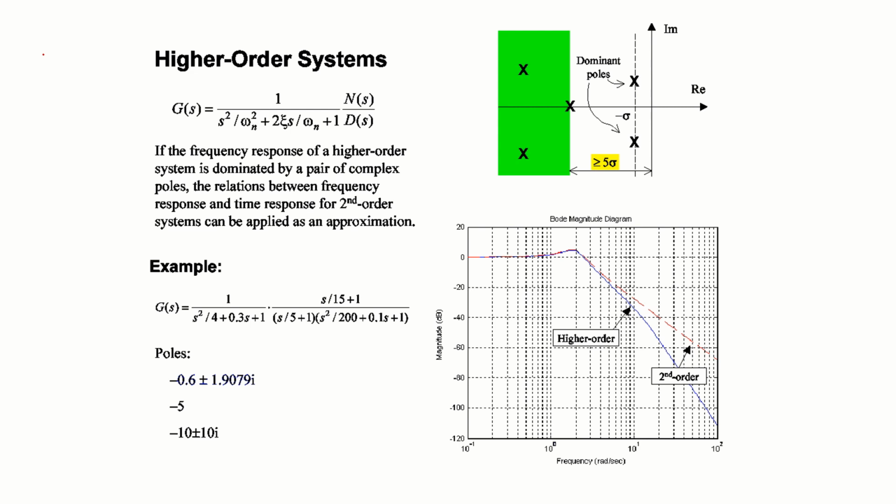What it means: suppose you want to understand the behavior of higher order systems. You see here in this system, suppose you have poles here and in this region. But these are the poles which control the system behavior. So this is what we call dominant poles. If the other roots are away, the response may decay faster, but these will not allow it to be faster. These are the ones which will be influencing. That's why dominant poles.